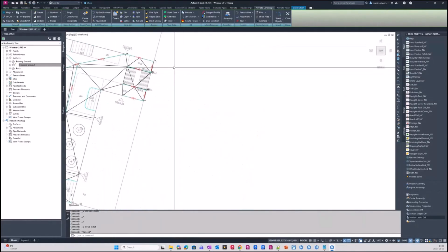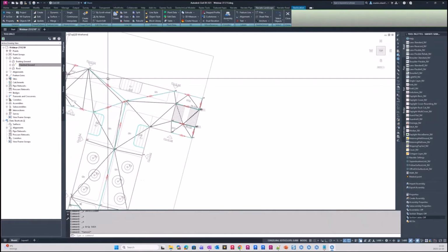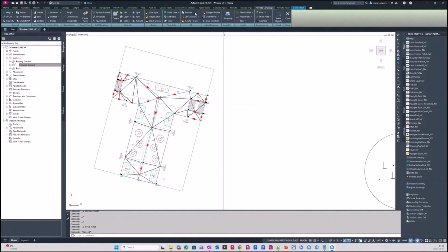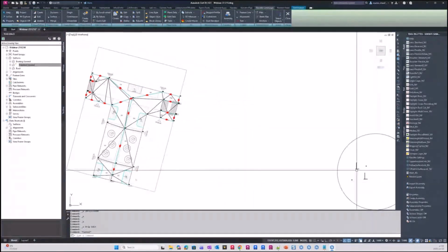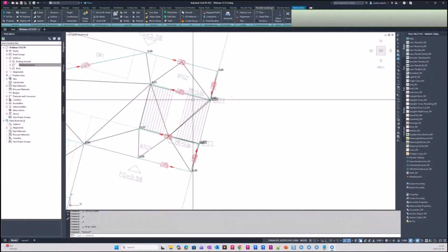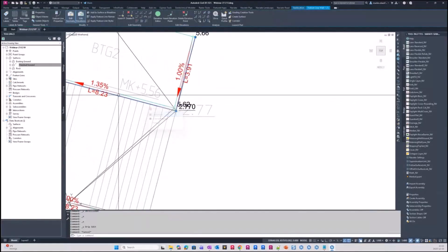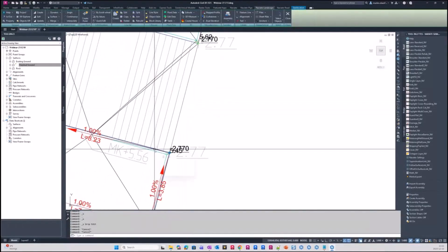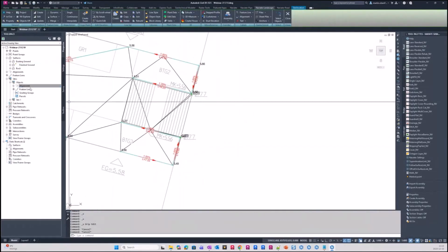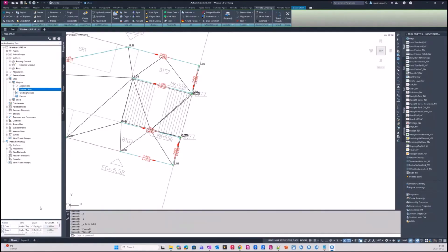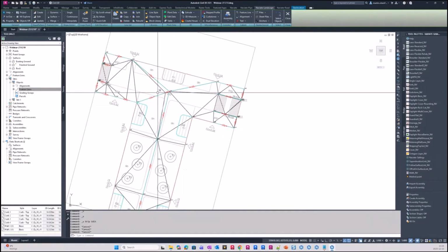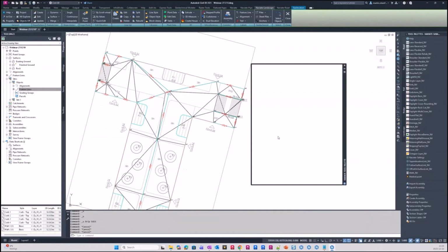And now we will look into some other functions here. This one, extrude, really good function to create 3D objects. So I have created some feature lines, just regular feature lines here that I will use. It's a good idea to create them if you're going to create objects, so you have them in a different site, so you got a good track on it. You can show that on the slope arrows as well. If you don't want to show the feature lines, you can use this object on off.